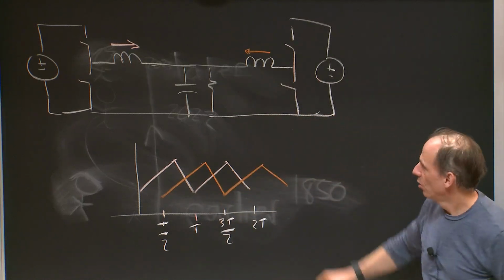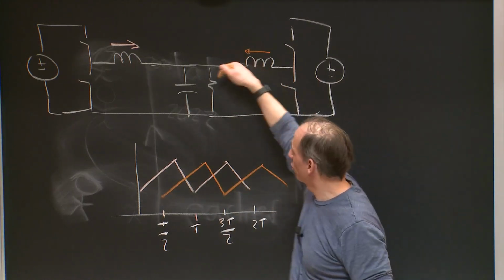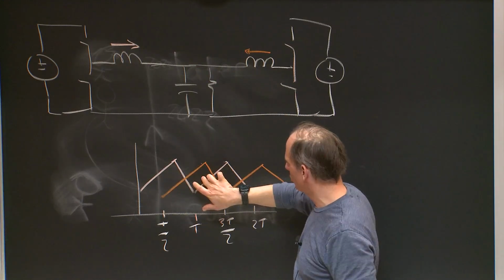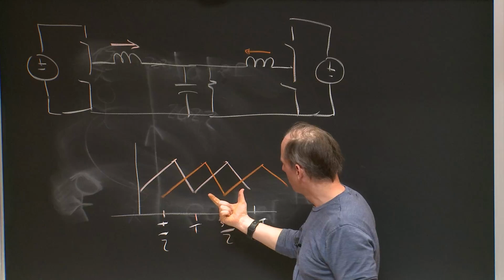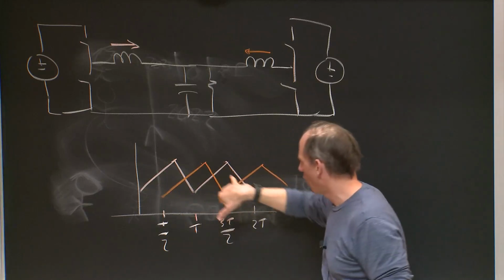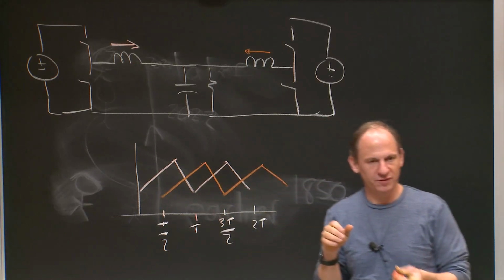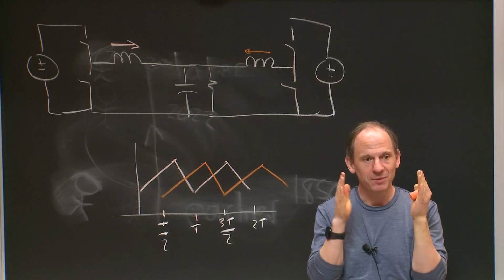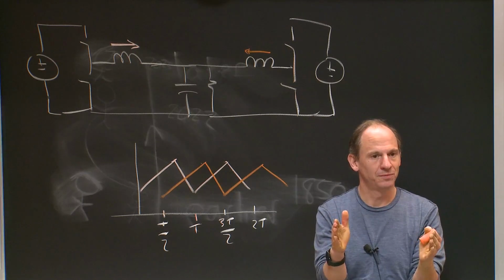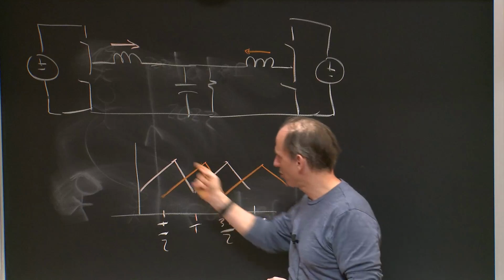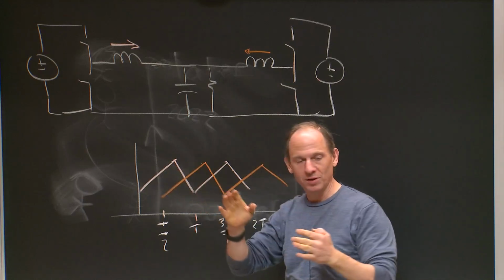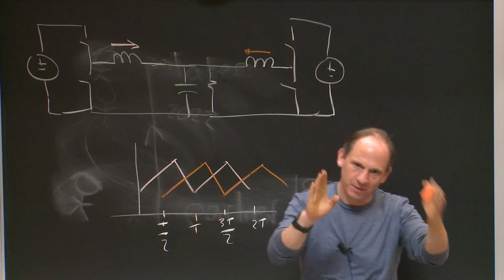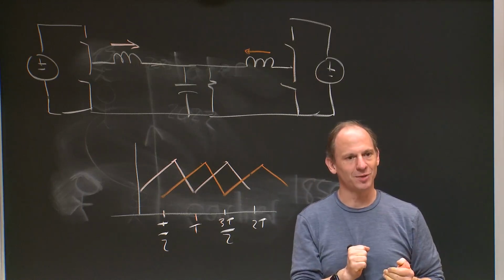What total current goes into the output capacitor? Well, it's the sum of this one and this one. But if I make orange and pink shifted by 180 degrees of the fundamental, the fundamental ripple will cancel. If there's second harmonic component in the pink waveform, the second harmonic of the orange waveform will be shifted by 360 degrees at the second harmonic.